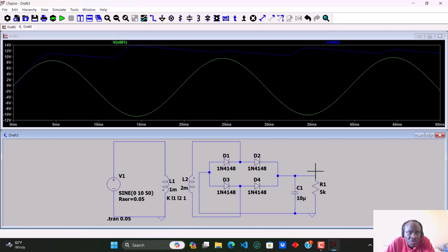Okay, thank you. I hope you'll also use LTspice and try to draw your own simulation circuits like this and see if you get similar things like the one that I'm getting here. Remember, when you are drawing this, you must couple your two inductors, and you need to use mutual coupling. Use 1. Very important here. You can use the same values that I've used here.